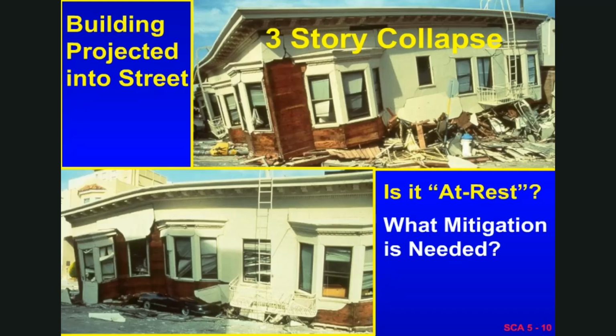One would, of course, when doing that, have an escape plan, have some idea where a safe haven within the structure would be, and one would not enter the void space except with few people, with minimum exposure, only when a victim was found, and only for a short period of time between aftershocks. One could do some shoring, but if the victims were badly hurt, one might not need to get in without that. So victims are going to be found in the upper space, but mostly in those two collapsed stories.